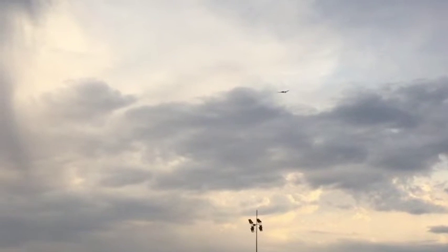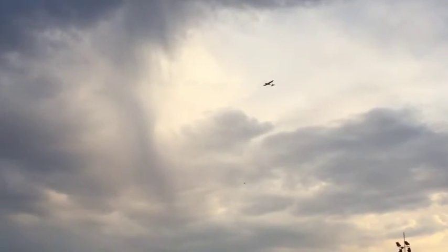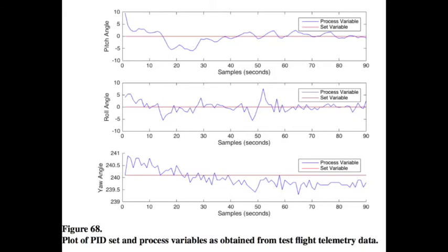So the flight stabilization was tested in a windy condition within spec, and the results are plotted here. The noise seen on all axes is basically the effect of wind disturbances on the aircraft. But in general, the flight stabilization worked well after the settling time. If you look at the pitch angle, it stays within 5 degrees after settling time.